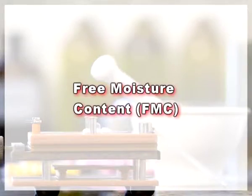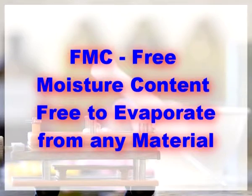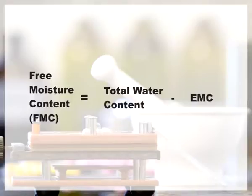Important parameter is free moisture content. Free moisture content is the amount of water that is free to evaporate from the solid surface. I have already told you that EMC is the amount of moisture content that is to be present in any material. FMC means free moisture content, which is free to evaporate from any material. So, FMC is equal to total moisture content minus equilibrium moisture content.